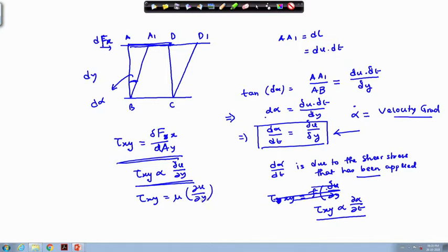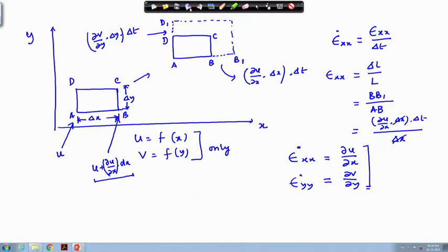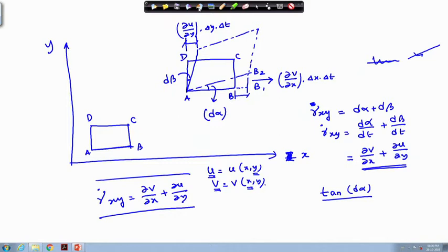So, this you can highlight, and this is also probably an important area where you should highlight what the non-Newtonian fluids are, where the dependence is not linear, and you can draw the usual figure for the dilatant and other types of fluids including Bingham. But that is not the whole intention, because viscosity you can understand. This viscosity actually is this proportionality constant and nothing else, but then again there are physical significances of viscosity which you can highlight.